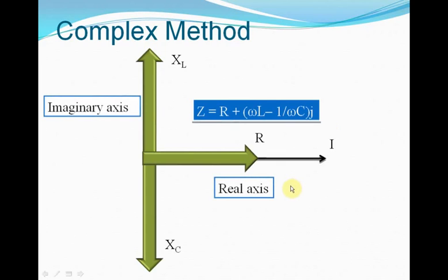Now this is just a depiction, and you don't need to worry about how exactly you can represent the impedance in the form of complex numbers. You see, this just simplifies the calculations when you have to add two impedances, subtract two impedances, or even depict the reactance because of inductors and capacitors and the resistance. Okay, so it's quite easy to depict it this way, rather than always saying that the magnitude is square root of R squared plus (XL minus XC) whole squared and tan phi is this expression. Instead of saying all that, you can depict the impedance like this.